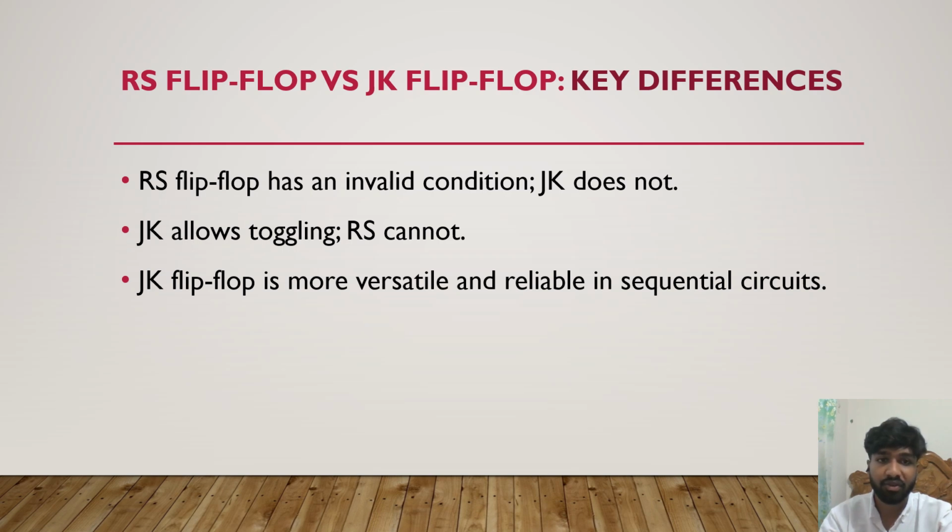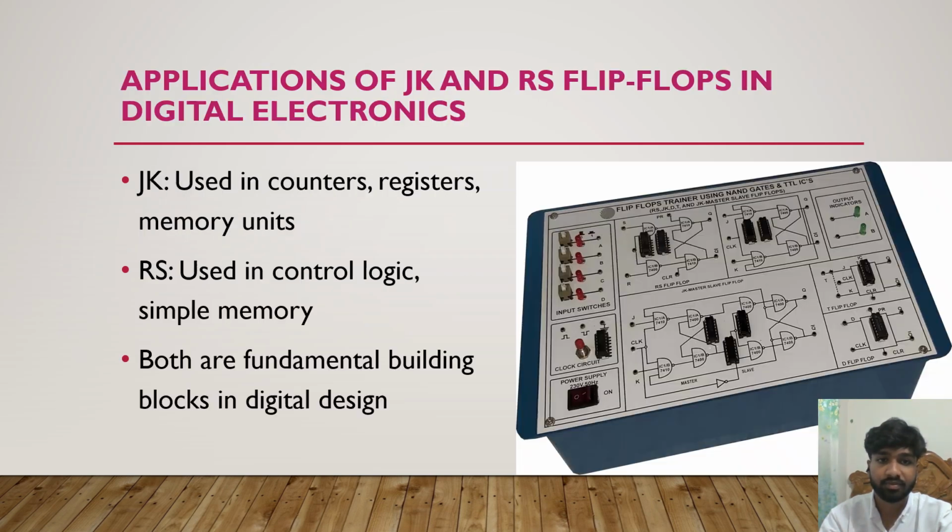Let's know the difference between RS flip-flop and JK flip-flop. RS flip-flop has an invalid condition that JK doesn't. JK allows toggling that RS can't. JK flip-flop is more versatile and reliable in sequential circuits.